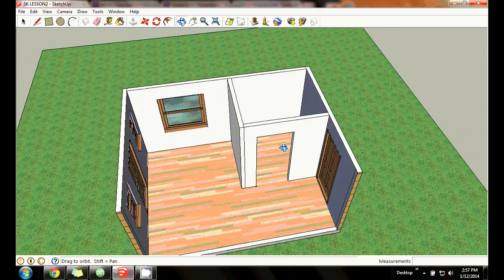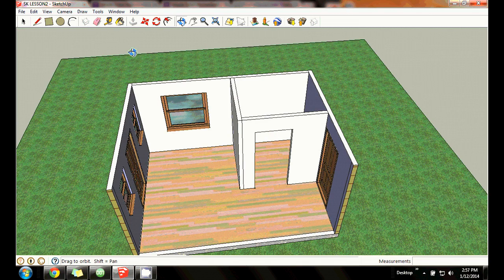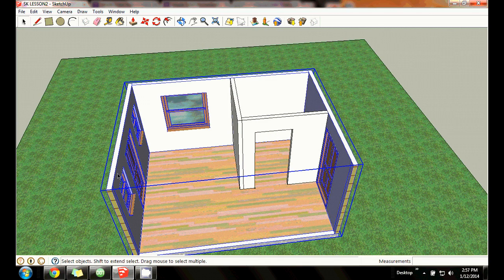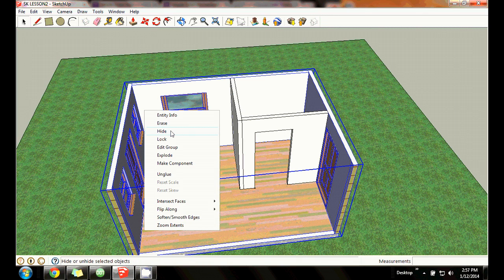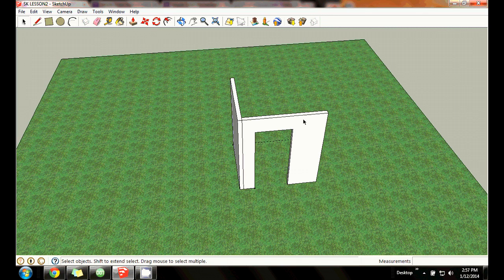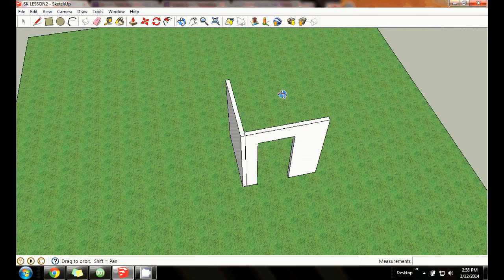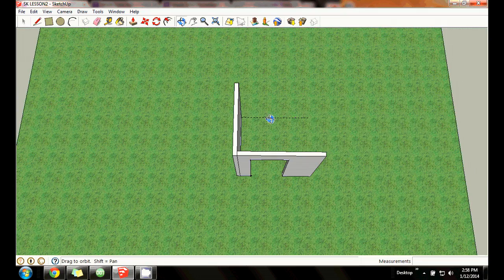That looks real good. Now, when I get done, what I'm going to be able to do is I'll be able to click on this module that we created and click hide. And now you see that my bathroom walls are all staying together. They're right there and working on it. When I get done putting in the toilet and shower and the other fixtures, I will turn this entire unit into a module.